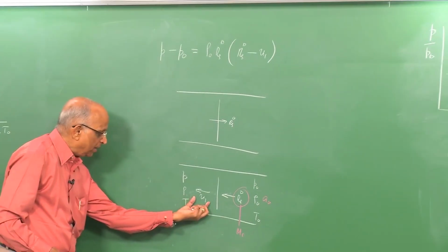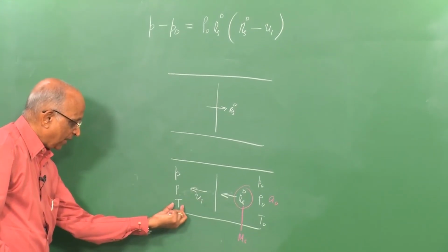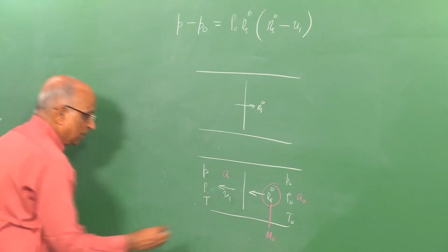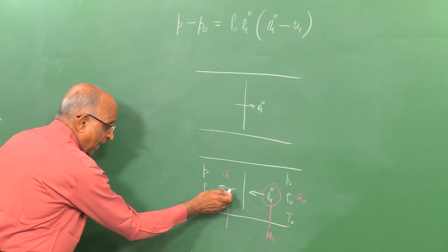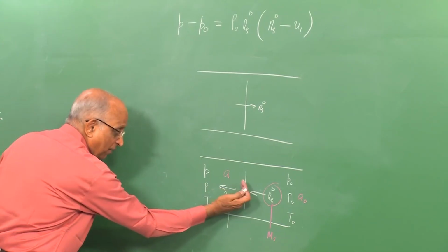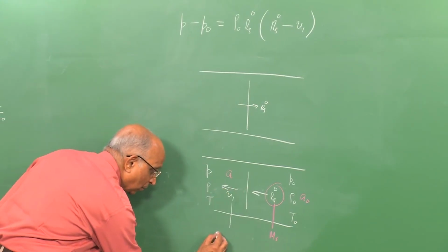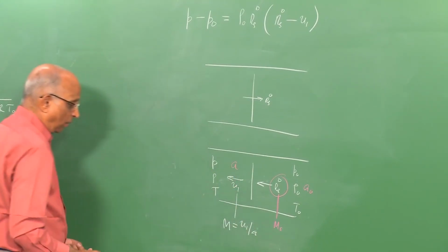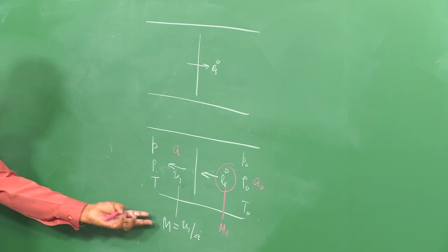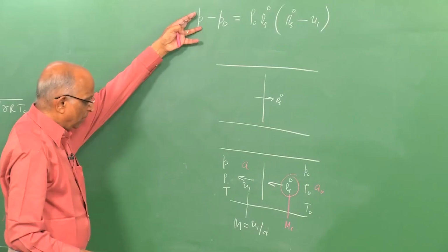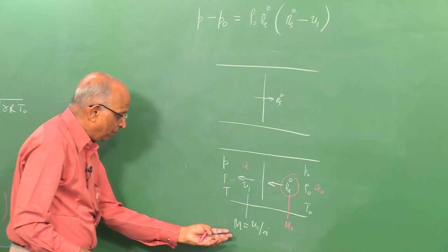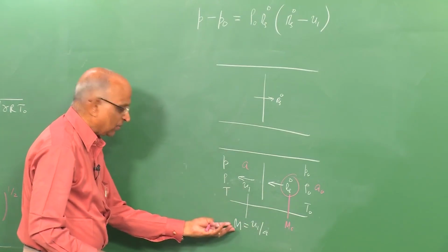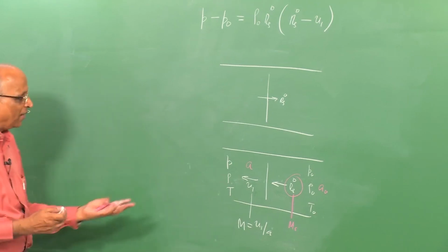The sound speed in the medium processed by the shock is at a higher temperature. Therefore, the sound speed is A over here, and therefore, the Mach number of the gases leaving the shock wave in the frame of reference of the shock wave is equal to m, which is equal to u 1 divided by the sound speed of this medium. I would rather translate this momentum equation into an equation which contains the shock Mach number Ms over here, and the Mach number of the gases behind the shock, and this is what I will do now.